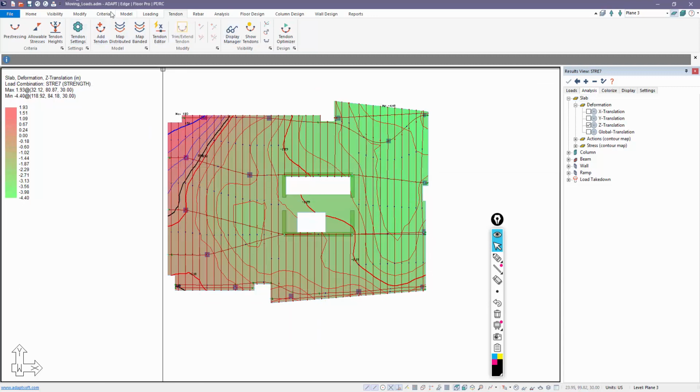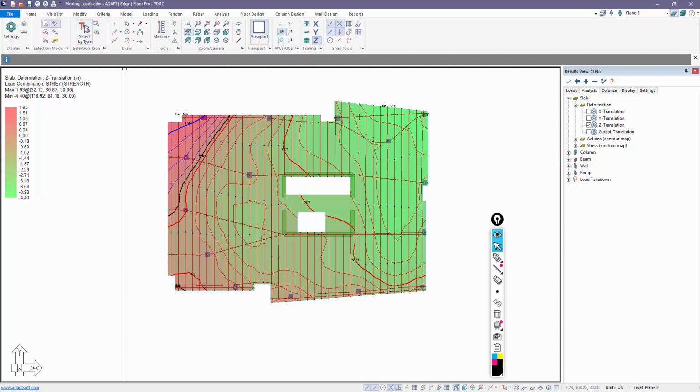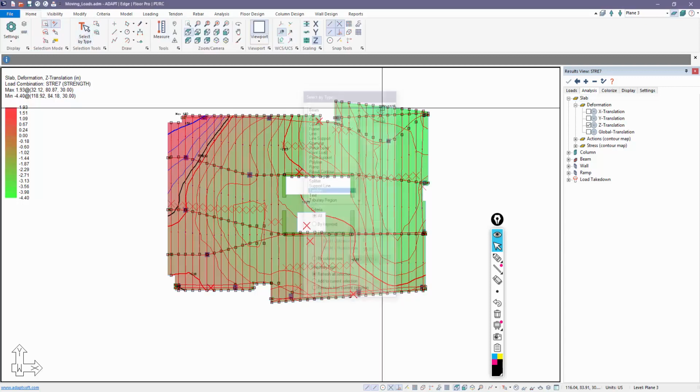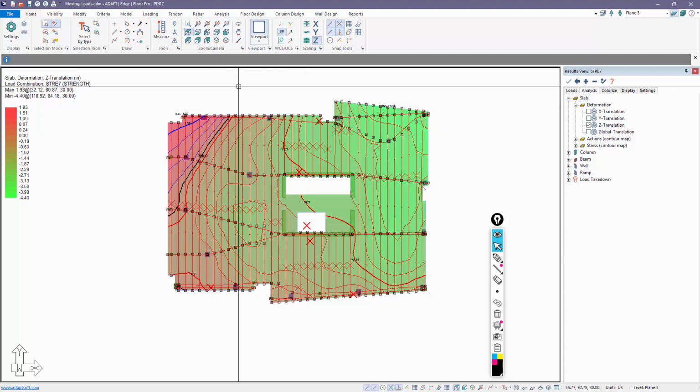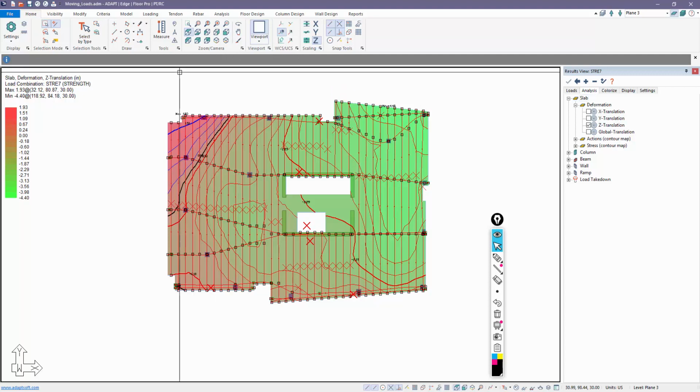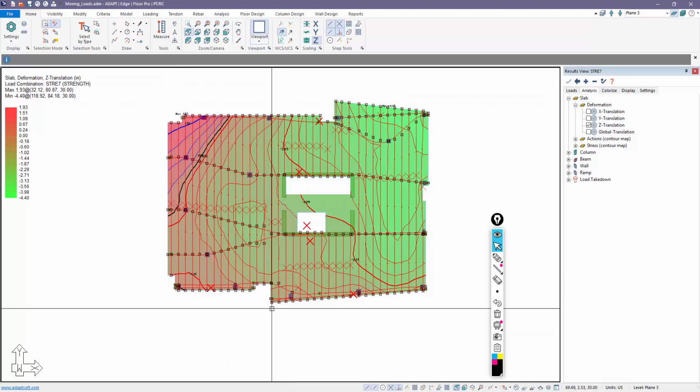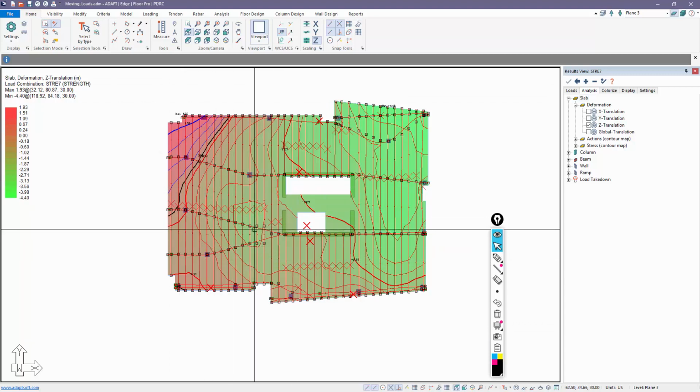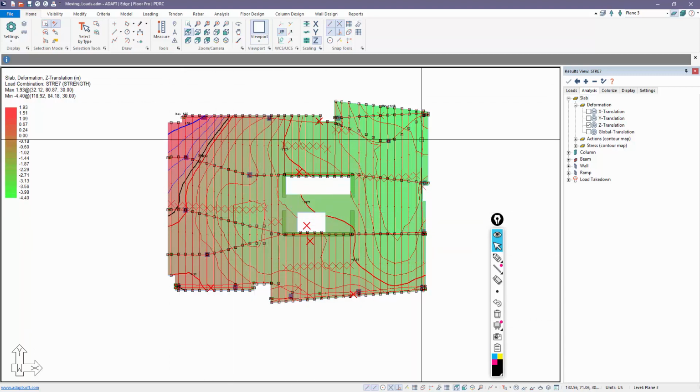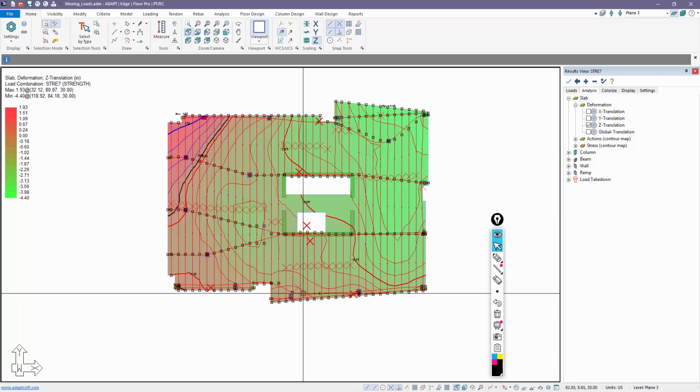For this example, we'll go ahead and just take these tendons, and I'm going to eliminate them from the model. So I'll just use my select by type tendon. And if this was a serviceability case and we had used pre-stressing, which is just the primary plus the secondary effects of the PT, the deflections would be fine. But because this is a specialized case, hyperstatic or secondary only, you get this deflected shape. So it's not unique necessarily to this model. It's unique to the way we solve for hyperstatic actions in the software.